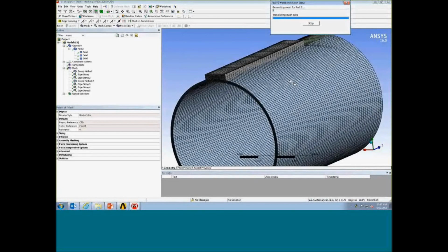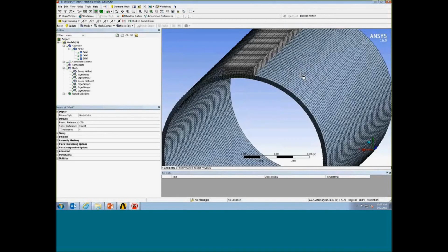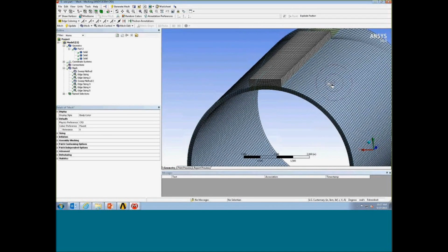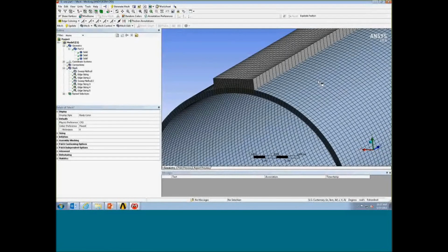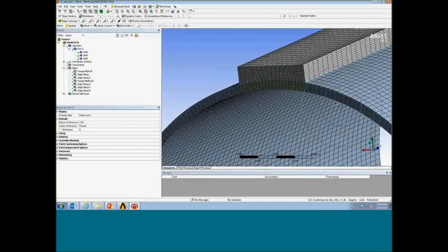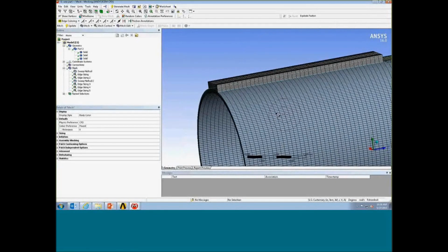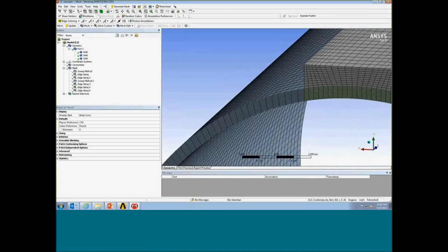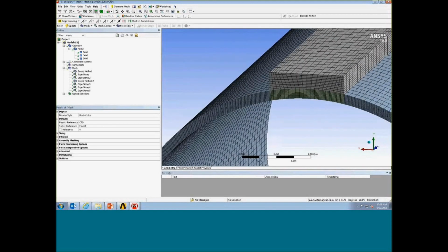You see, we talked about the previous mesh, tetrahedron plus prism layers. It took about 3-4 minutes to generate, and here it's done in about 10 seconds. And the mesh, you can see here, is all hex elements, okay? All hex elements, and I generate enough resolution. I specify like 10 elements across the gap, and 10 elements in the gap region.